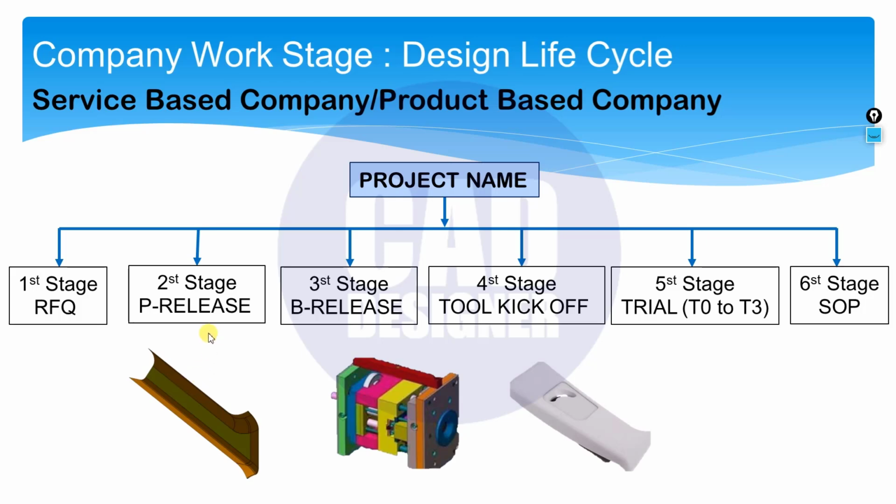With that proto, they check aesthetically, and also whether the features added, locators, snaps or screw bars, are properly assembling or not, or whether there is a play, whether these snaps are properly inserting and working as per requirement or not.